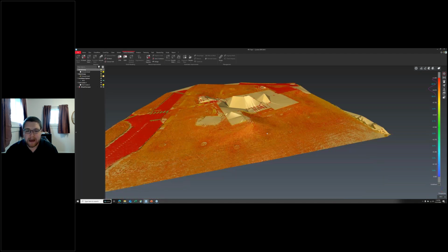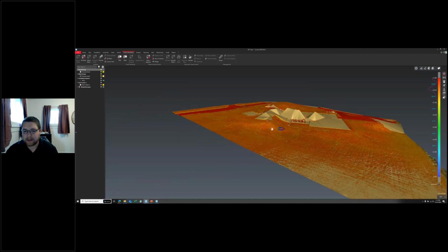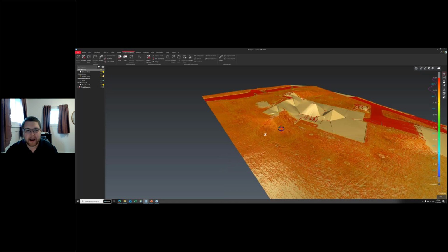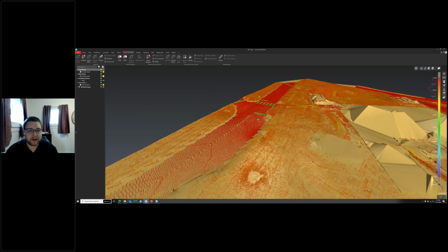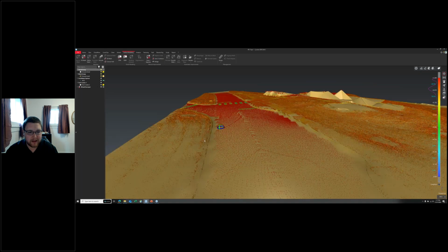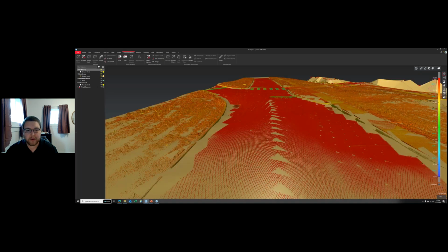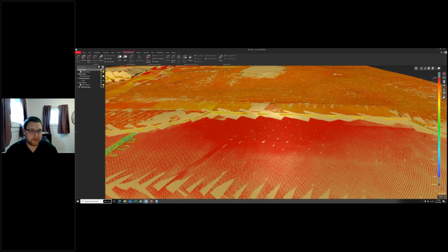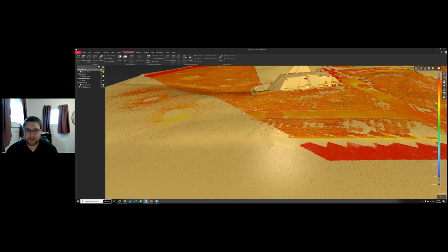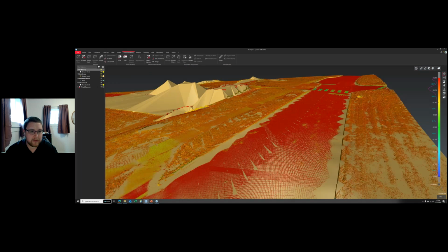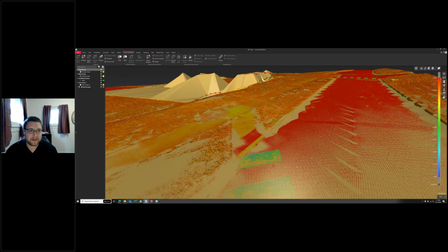And right off the bat, because this is a lot of rolling hills, it did a really good job picking that up for me. Things like curb, those sharp edges, it doesn't always pick up, of course. So those are where those break lines that I extracted come into play. Those are always still needed, right? People still want to see where the sidewalk and the curb is.